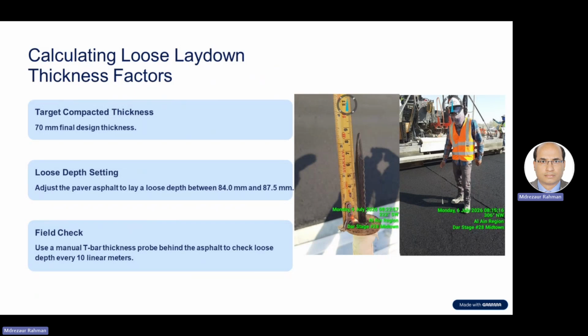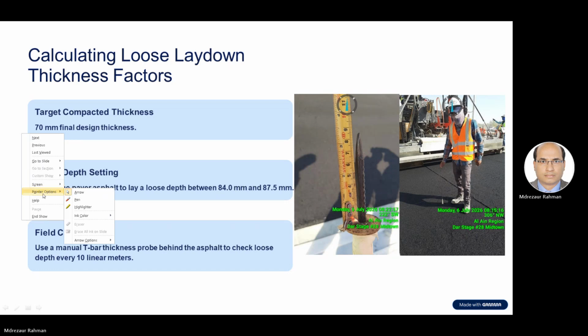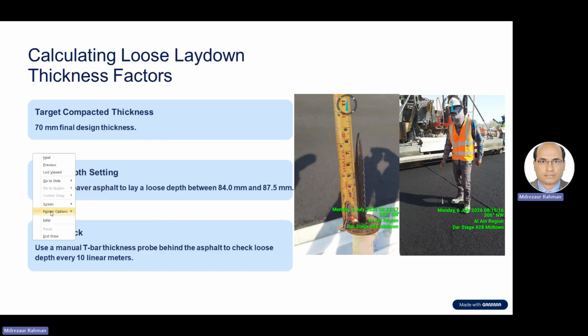Okay, now I'm coming to what Engineer Asif told just now. Bitumen grade 60/70, if the temperature is more than 163, the bitumen will be burned. And the asphalt looks dull. The small aggregate you will find is brown, like coffee color. So the maximum temperature will be 163.